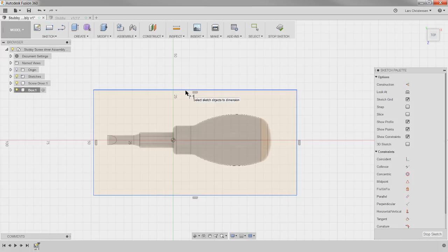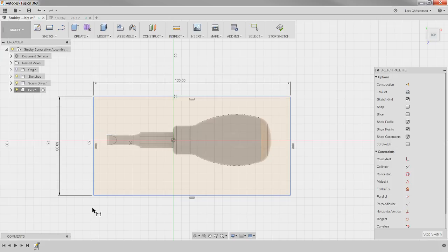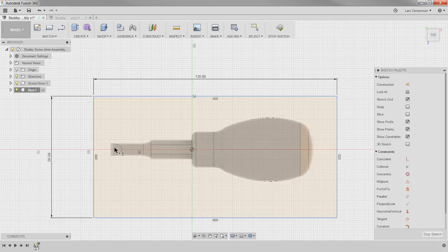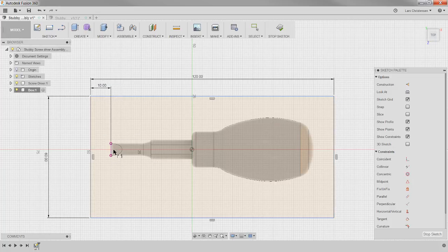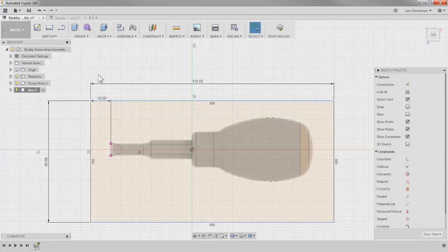So D for dimension. You could try to offset from edges out, but a box normally has some kind of standard size, so we'll probably do it like this, and then from this point I might locate it by adding some edge constraints to it. Oh, here's another neat trick I wanted to show you. See how right now the box can go up and down? Sometimes I do this. Hit alpha line, snap to the midpoint. It's going to show up with a triangular shape. There's the midpoint. I'm just going to draw a line horizontal, just like that. So that is sitting right there.